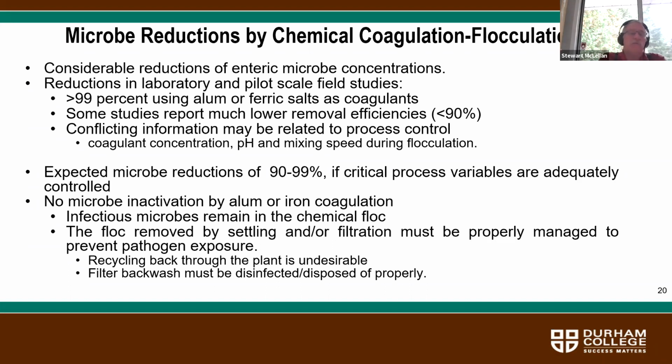So, this is part of the reason why we have chlorination systems for the removal of microbes, because, yes, you do have some efficiency in the removal of bacteria and viruses through coagulation and flocculation. These bench scale studies indicate it's not 100%, and you do need to be cautious about the presence of microbes in your effluent discharge.